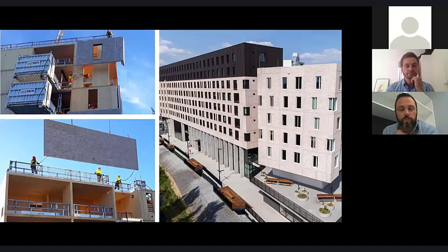So the tower crane was not active because the structure was up, and they were dropping the prefab panels in after the structure was installed, and that was connected directly to the CLT, be it to the slab or through the wall or into the wall, not knowing the details exactly. But you can see all the similarities to the previous US project that Nathan showed with the brick facade, and it's showing the different methodologies that can be looked at from a design perspective with a hotel in order to manage a facade component.